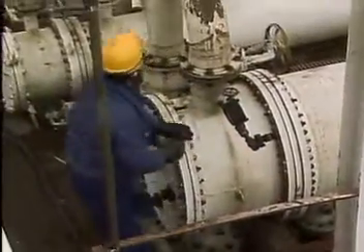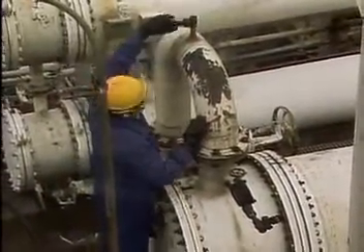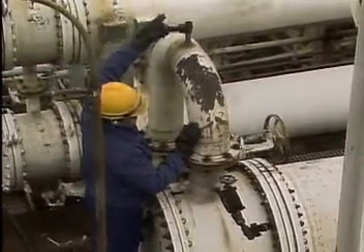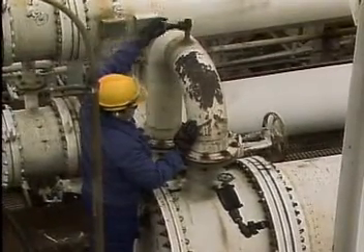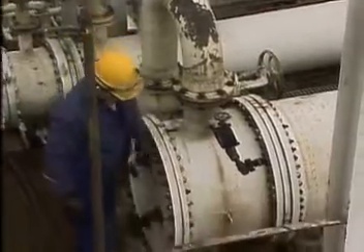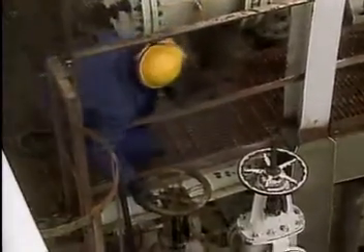The corrosion weakens the metal until a leak forms. Regardless of how gases get into the heat exchanger, the unit must be vented to allow them to escape. Repeated venting may be necessary to ensure that the heat exchanger remains free of air and other undesirable gases. However, excessive venting can cause its own problems. For example, each venting may allow a small amount of the process fluid to be lost from the process. This reduces the efficiency of the process.